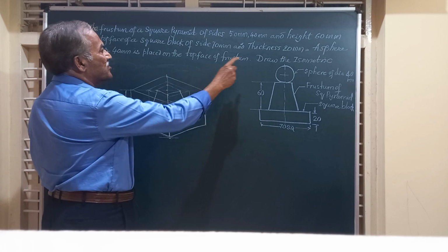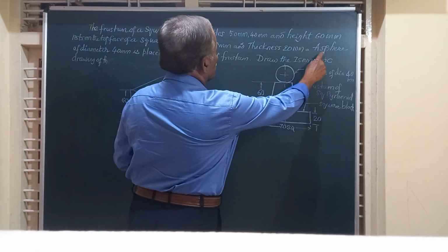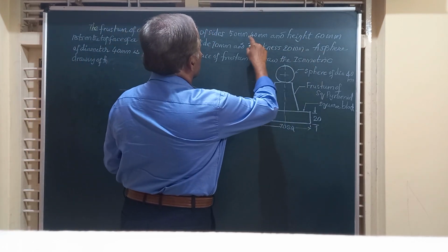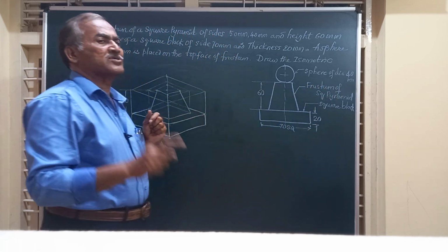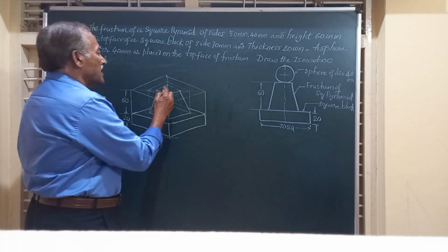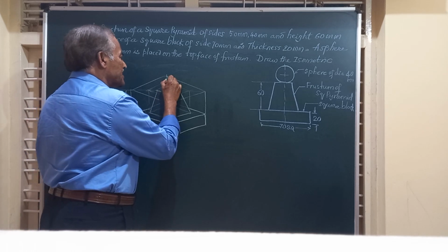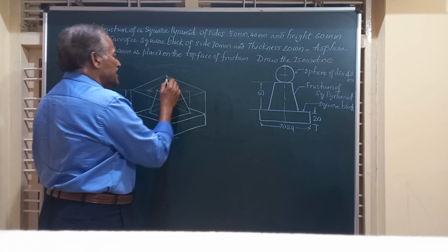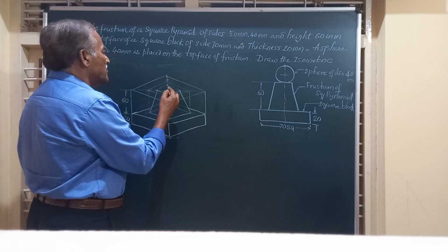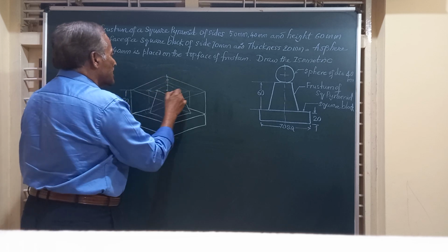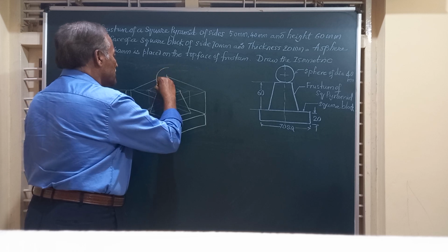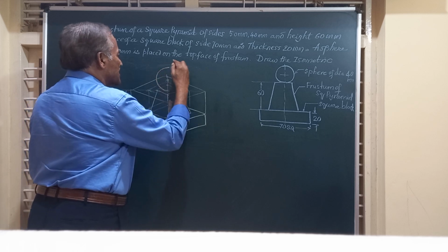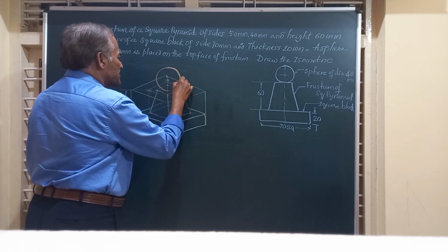The height is equal to the isometric height, that is the diameter is 40, radius is 20. So we have to take isometric height of 20. So taking that as the center, we have to draw a circle from this center. So friends, you are going to have a circle written in this fashion.